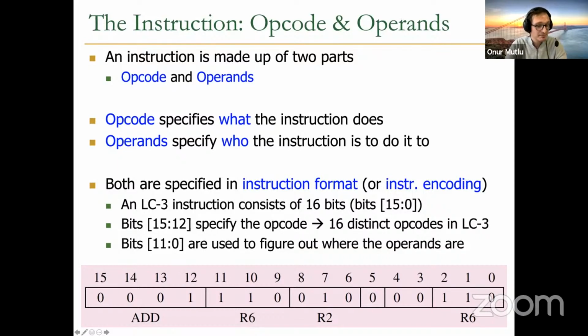And by decoding the bits over here, the computer finds that out. By looking at bits 15 through 12, the decoder in the computer says, oh, this is an add. Now I know how to interpret the remaining bits. After the add, this is the destination register, and then maybe I look at some other bits to determine the source registers, as we will see. But you can easily decode this instruction by just looking at the bits in logic structures, right?